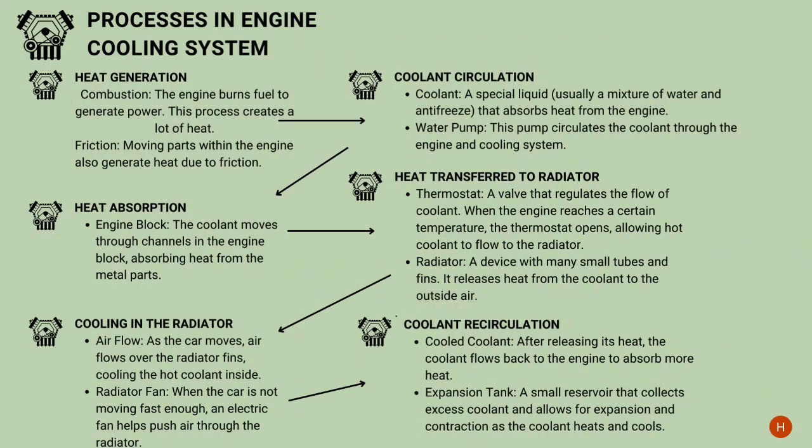After the coolant goes through the radiator, it maintains the temperature and flows back to the engine to absorb more heat. And the expansion tank is a small reservoir that collects excess coolant and allows for the expansion and contraction as the coolant heats and cools.